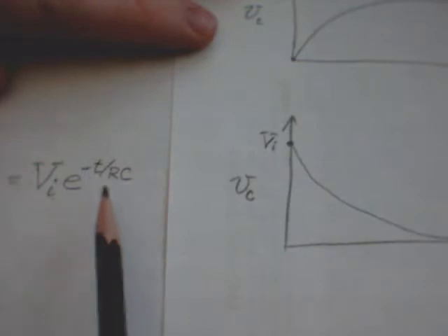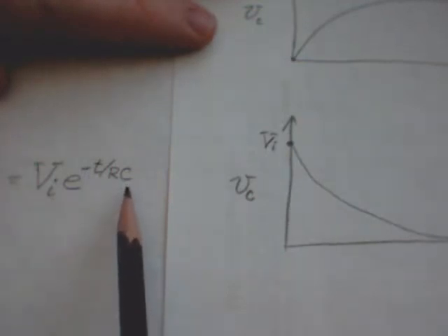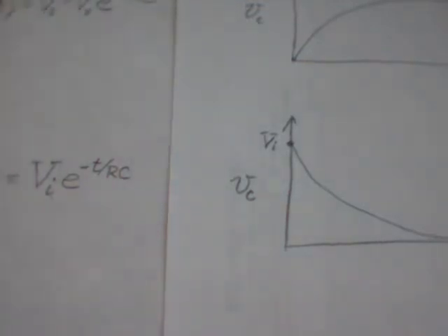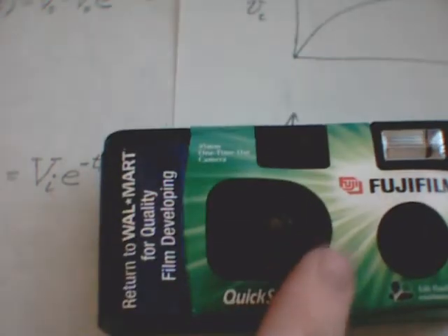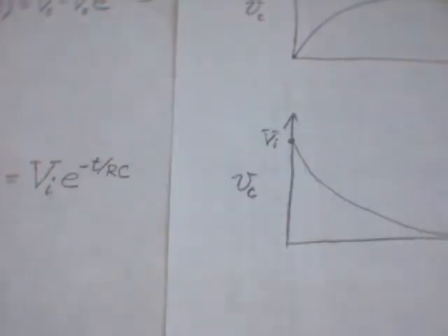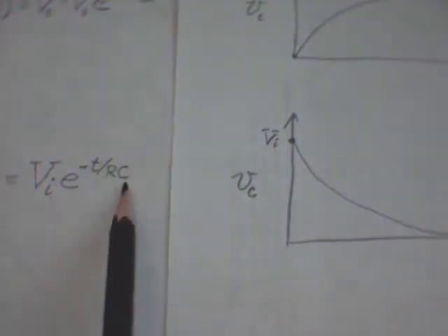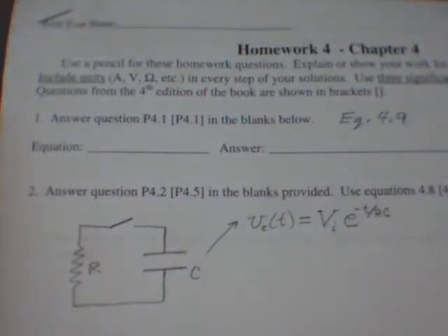And the length of time that it takes to discharge a capacitor depends, again, upon your choice of resistors and capacitors. You might remember that in Engineering 111 and 112, if y'all had that from me, we took a screwdriver and put it across the terminals of the capacitor that was in this device. Because the resistance of the screwdriver was really low, that makes this time constant, that's what this is called, by the way, the RC time constant, really short. So with that being said, here are a few short notes you can add to homework 4 to get you going.